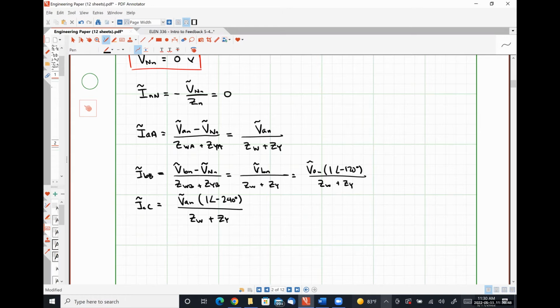So we have a large three-phase load and then a smaller single phase load that's ancillary to that. So what we'll do is every building, the first building will be connected to the A phase. The second building, the ancillary load will be connected to the B phase. The third building, the ancillary load will be connected to the C phase. So that we effectively rotate them through so that we're balancing things out.